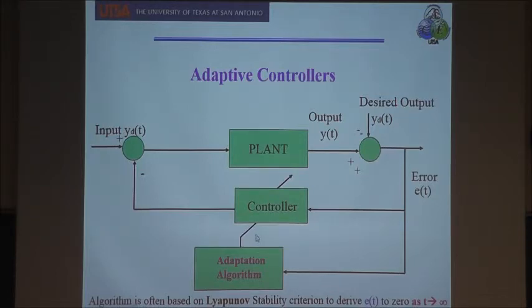We can mimic an expert like a control engineer and put fuzzy if-then rules here in place of this algorithm, and online in real time change the gains of the PID. If the error is low and change of error is high, then KP is equal to this. Simple as that. And this is coming from an expert operator, who may be retiring next month, but before he retires, we can take all his knowledge and put it into a chip. It's done. It's been done for 20 years already. Okay? And that's how it works.